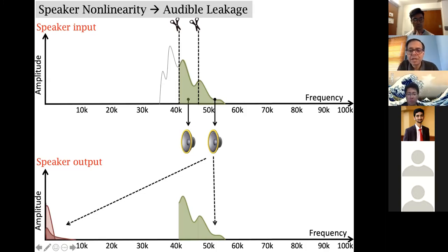Because if you think about it, when you take the second green slice, if you take adjacent pairwise frequencies, the first frequency and the second frequency, they have a gap of epsilon, right? So that will go to epsilon frequency in the audible range, right? So every time you take a slice, it's actually going and sitting from 0 kilohertz to the bandwidth of that slice. So they're sitting on top of each other.